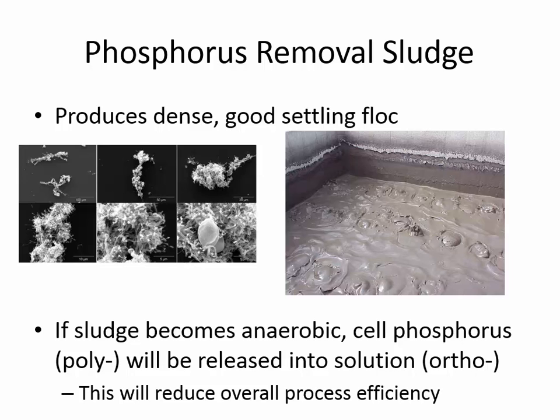And so that's just one of the operational concerns: when you accumulate the sludge, you're going to be taking it off the bottom of the clarifier. When they temporarily store the sludge before dewatering it and drying it, they really have to aerate it. Otherwise, you've just got a water pollution problem again. You've got a higher concentration of dissolved phosphorus than you had before. So you don't want it to go back into solution.